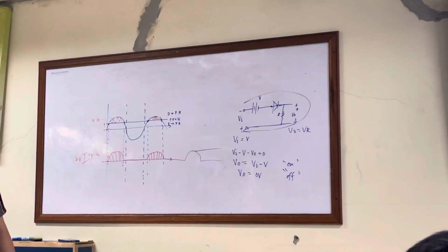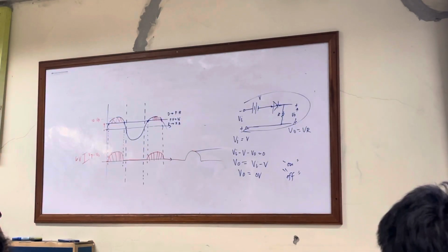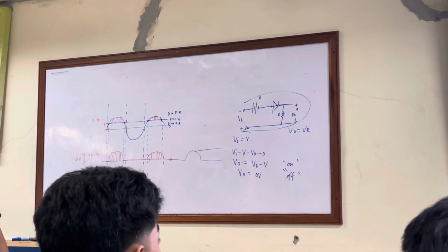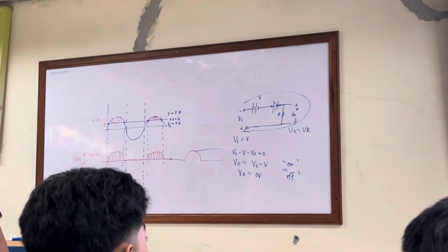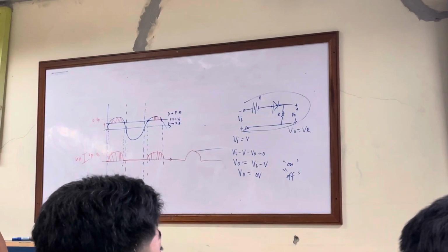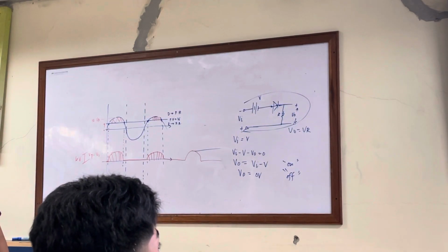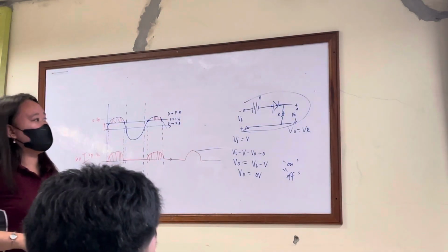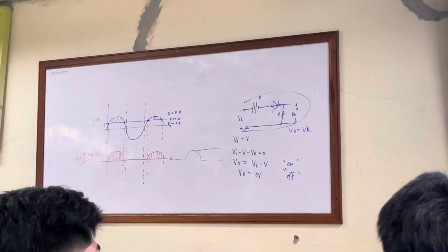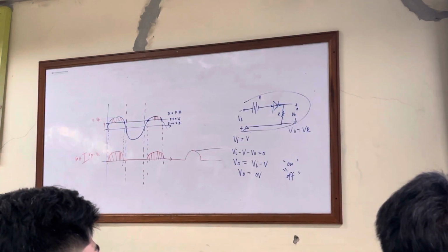Okay, example here. Determine the output waveform for the sinusoidal input of this image. The output is again directly across our resistor. For the positive region, the VI and the DC supply are both applied, but this time the DC tries to turn off the diode.